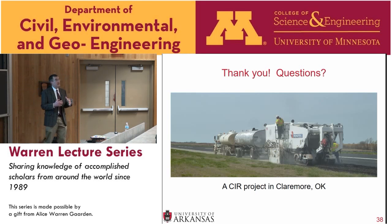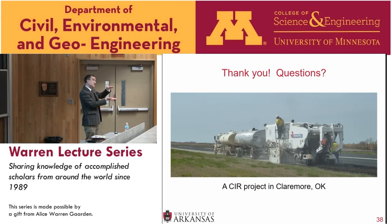We believe that there are a couple important phases of a CIR paving operation. One is physically milling the material and mixing it, and then making sure it can get placed. And during those steps, you need to be able to continue to move the material around, and you don't want it to get stiff. You want to be able to move it all the way until it comes out of the back of the paver, and then you physically start compacting it. So once you start compacting it, you're no longer trying to mix it, you're just increasing the density.